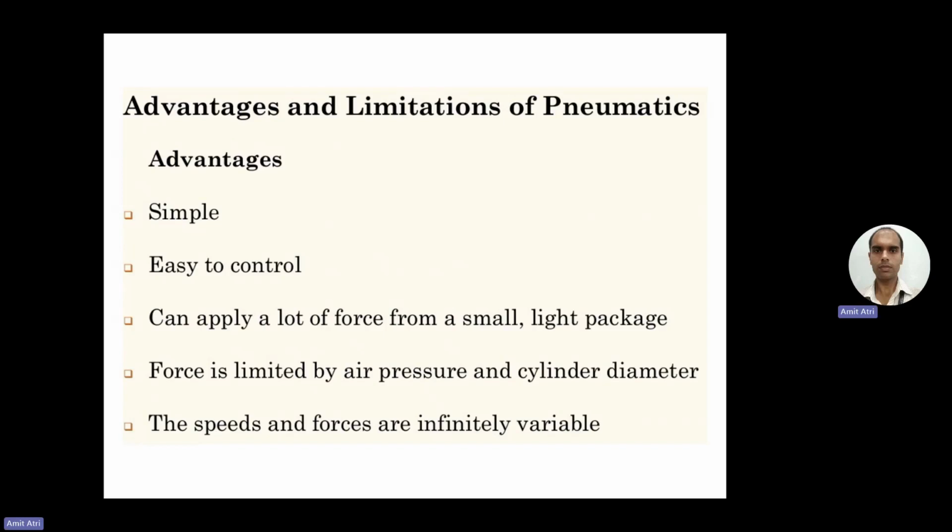Advantages include their simplicity, they are easy to control, and they can apply a lot of force from a small, light package. So the size is small and we get a larger force, limited by air pressure and cylinder diameter. The speed and force are infinitely variable, so we can vary them over a large range.